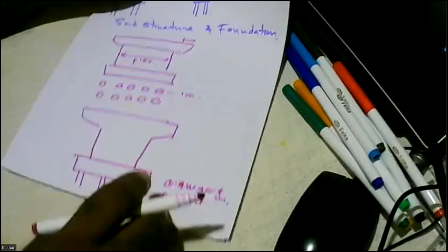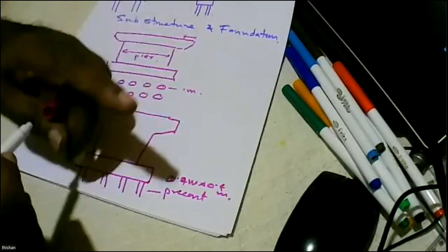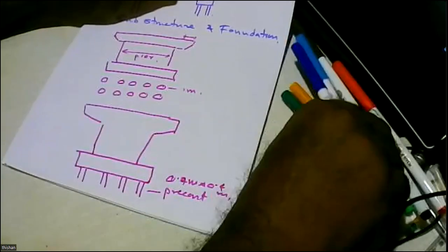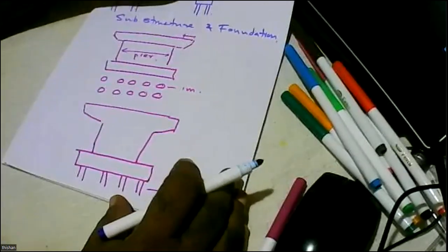Generally, I do not agree with using precast piles, because we have bedrock, weathered rock, fractured rock, and then basement rock. When we are doing the piling with cast in situ bored piles, we can actually go deeper into the basement. But in the case of precast piles, we are most likely to end at this level.